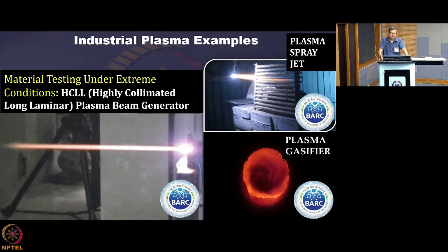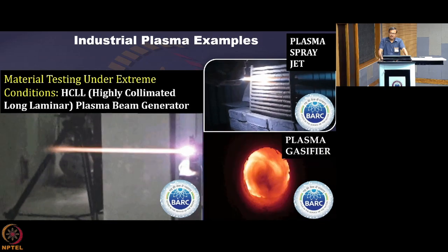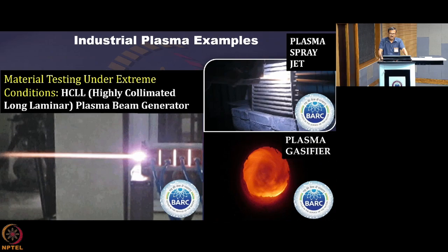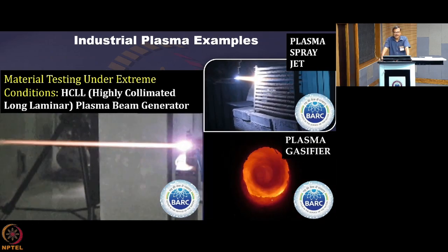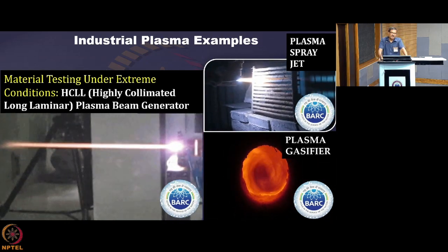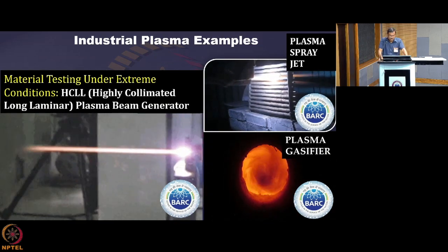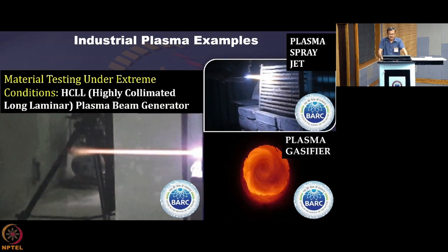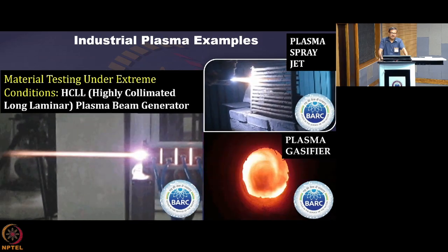Suppose you want to sinter some high temperature material and you are looking for a container. Normal materials like molybdenum and iron, or graphite, may be good for holding that kind of temperature, but they may not be suitable because they can react with the material. So you will not be able to take the material out of the pot where you are melting it.